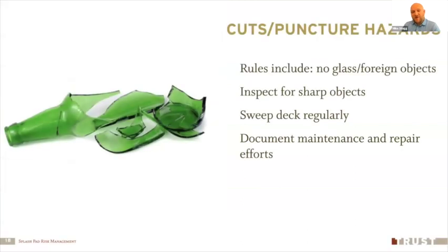What about cuts and punctures? Okay. Gotta include rules. This has to be on your rules. No glass, no foreign objects. Okay. No glass around the splash pad or on the splash pad or in the area around the splash pad. Okay. Make sure you inspect for sharp objects. When you open up the facility each morning, make sure you're walking it. Make sure you're walking the splash pad and making sure that there's no sharp objects or protrusions or things that kids can get cut or punctured on.